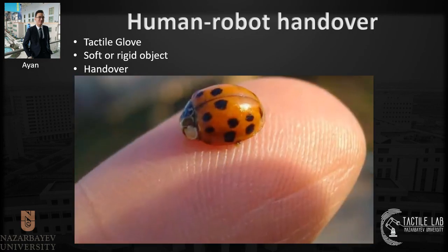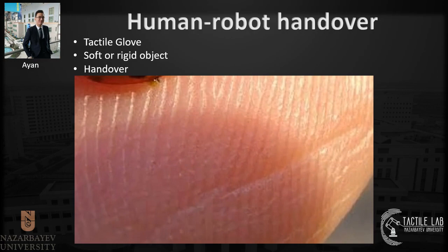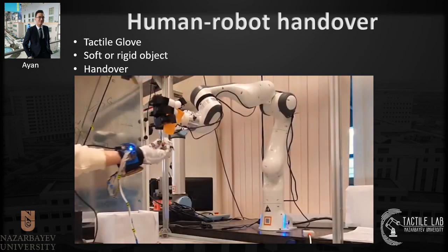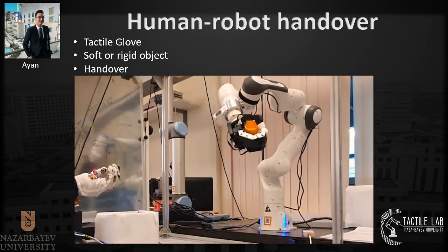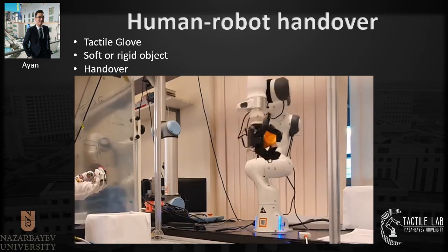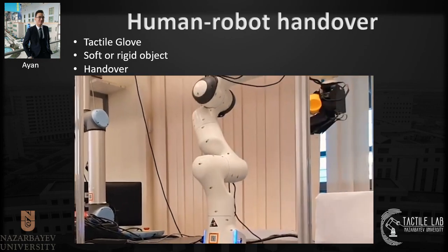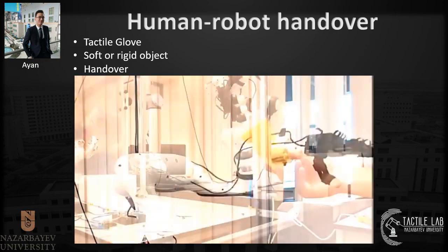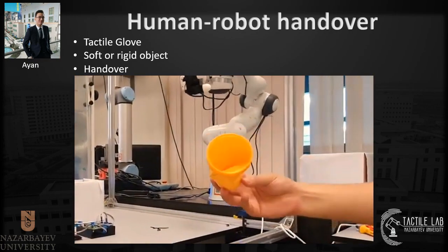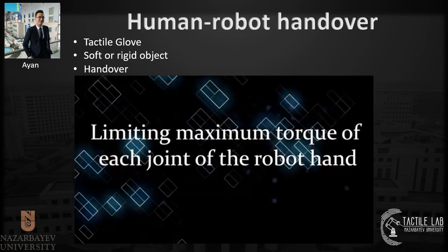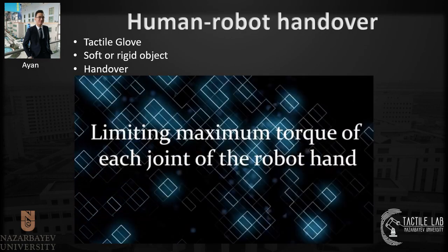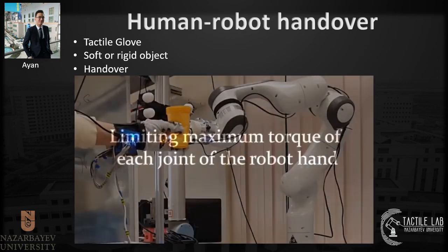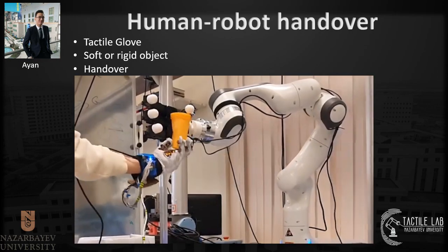A wide range of sensory inputs allow humans to distinguish deformable and fragile objects from rigid ones. Accordingly, humans adapt their grasping force to avoid damage and, at the same time, slippage. Excessive grasping force may damage soft or delicate objects in the handover process. Therefore, our idea is to set an upper bound of grasping force in order to prevent undesirable deformation of soft objects.